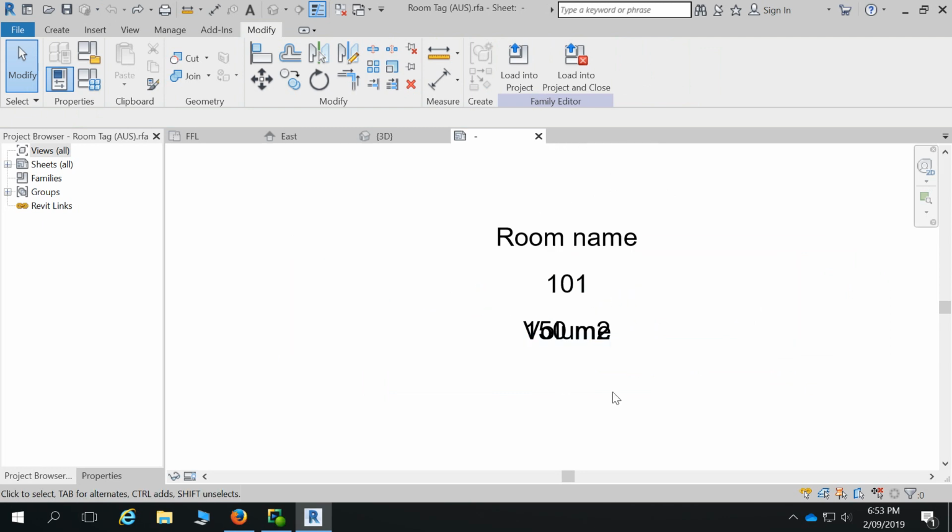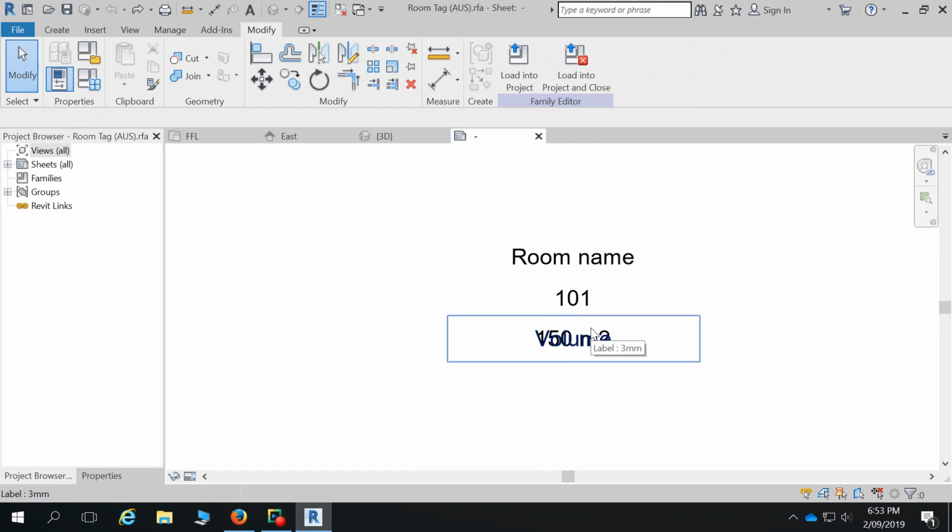So if you place your cursor over it and hit the tab button once, the tab button cycles through to the layer beyond. And now if I click that, it's only selected the meter square, it's the layer beyond. So we use the tab a lot when we're doing walls and we want to pick the floor below a wall or the door. There might be 10 layers on top and we can tab through and cycle through. And how we know when we've got multiple things cycling through is, remember down the bottom left hand corner, you've got that little prompt that tells you what it's picking.